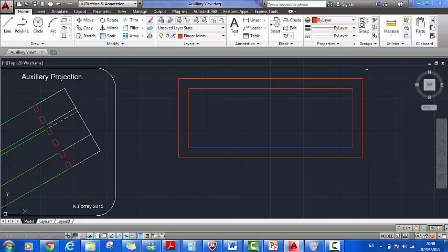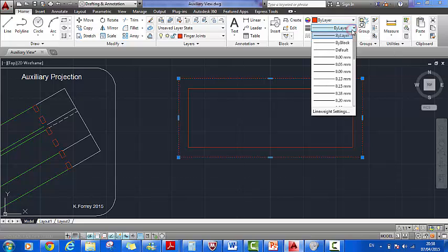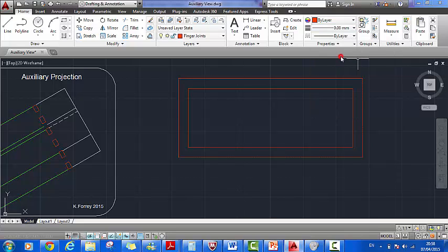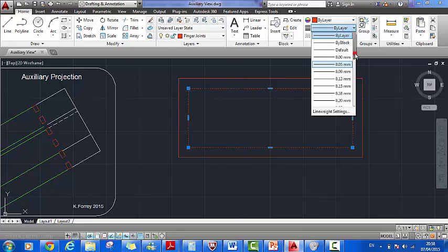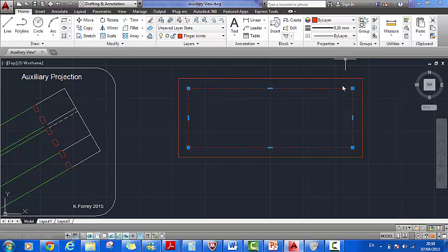Okay. So select the object that we want to vector or to cut. We can go up to bilayer here and select it as zero thickness. Now that is going to be selected as a vector cut. And select the inner rectangle, and if we want to engrave this at a thickness of 0.3 millimeters, select 0.3, and that is it done.